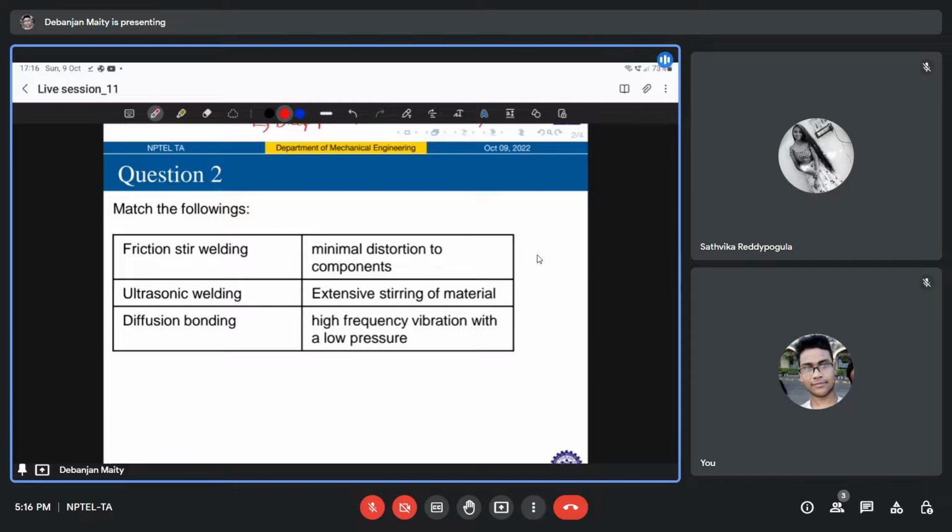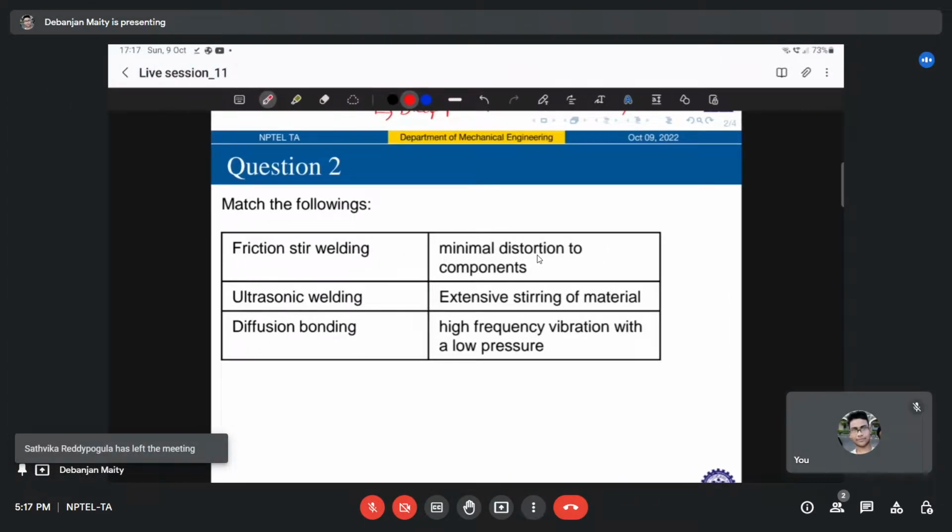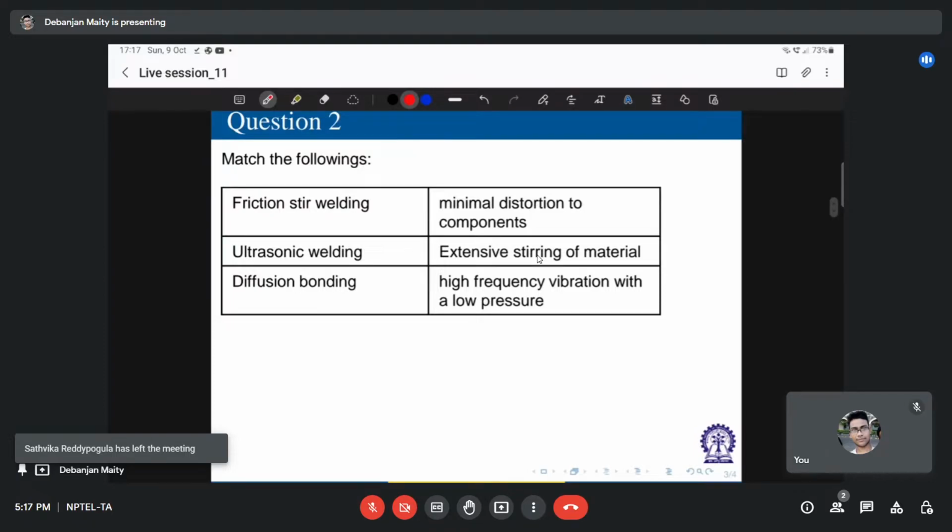One example is aluminum heat sinks to alumina substrate, and it is most commonly used for attaching beams or rods to bulk or sheet components. I have described this friction stir welding earlier also. You will have a cylindrical tool, which can be pinless or with a pin. So let us say we have some pin.